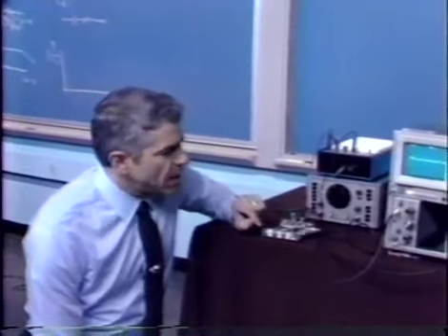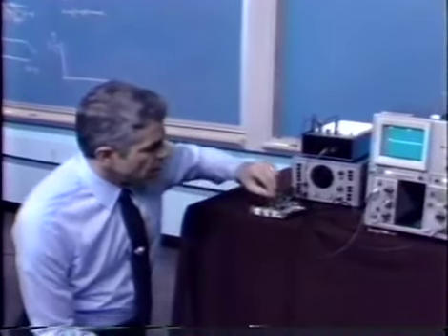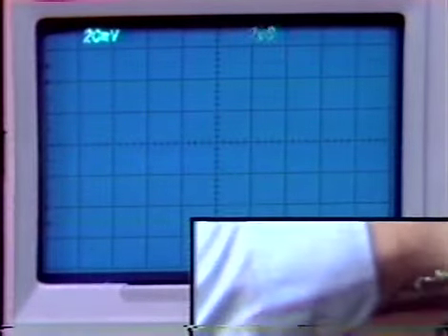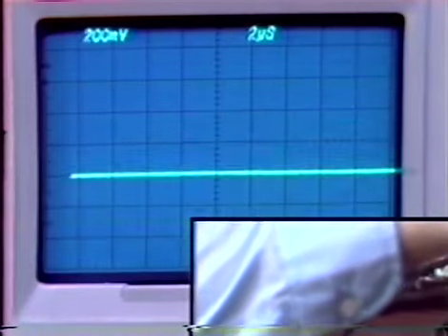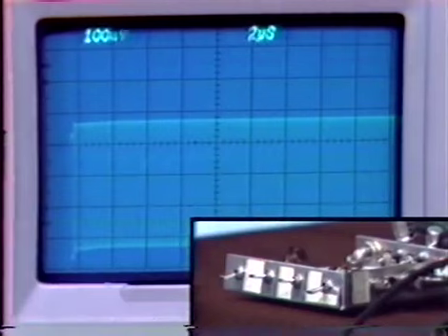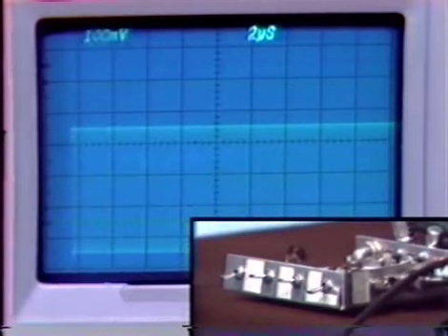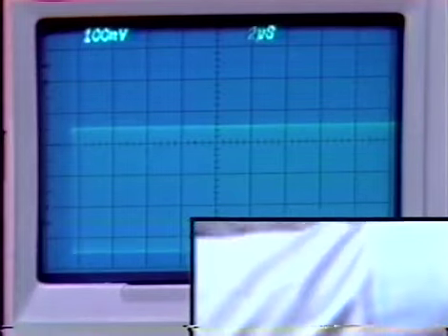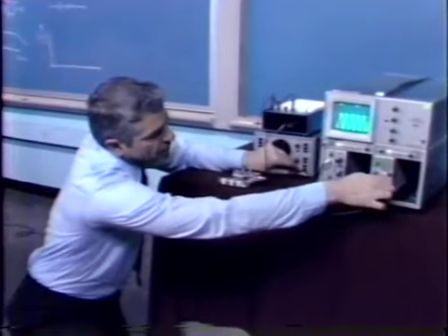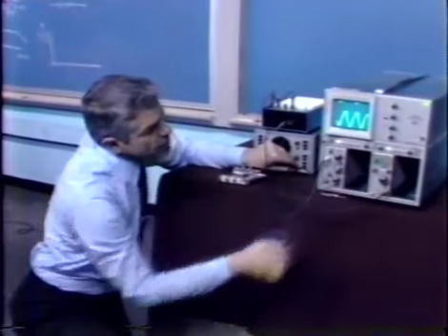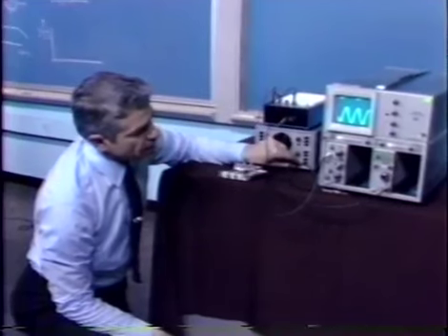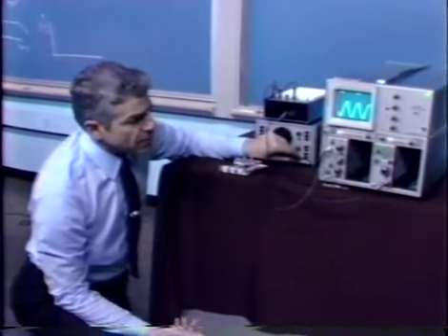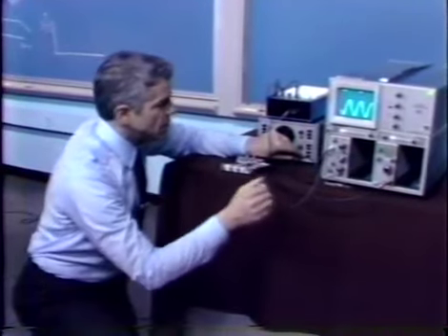What happens if we take the capacitive load away? Well, the system goes unstable. We can see that. Let me go back to zero capacitive load. And we notice even if we eliminate the input, the amplifier is oscillating. Here the amplifier is oscillating at quite a high frequency, several megahertz, reflecting the fact that we've taken away the capacitive load, which is really necessary for stabilization when we use this sort of compensation.